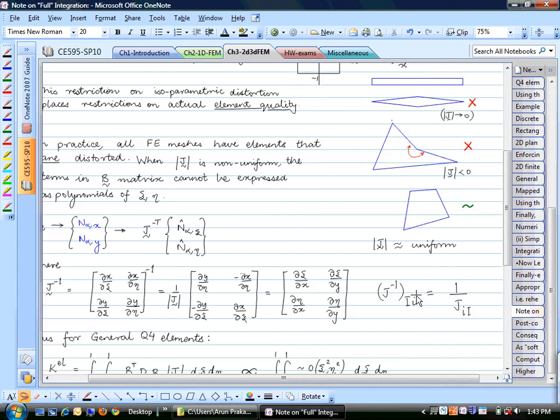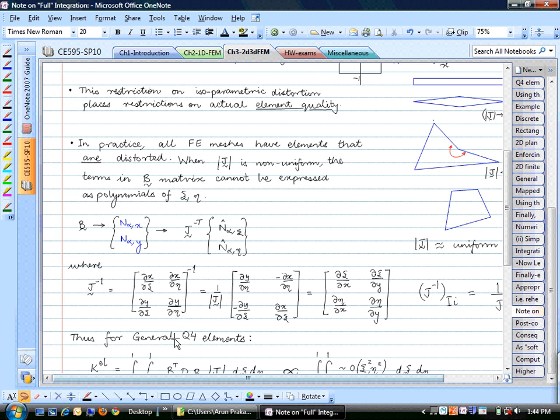So what we are saying is that if you're trying to find the components big I comma small i of the inverse matrix, they are nothing but 1 upon the component of the original Jacobian matrix. Okay. So it is this relationship actually which allows us to simplify the form of the B matrix, and that's why all those error measures, or all those orders of approximation that we came up with last time, were giving you valid results.